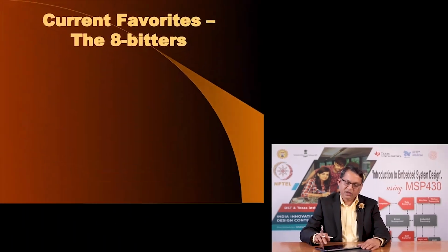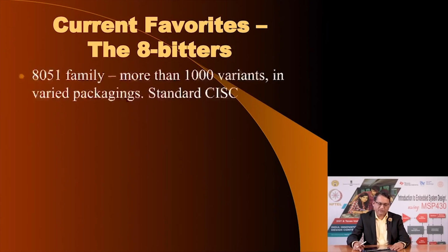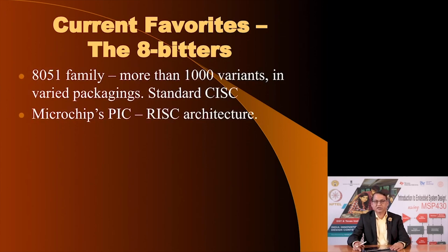So, this is a list of some popular 8-bit microcontrollers. One of the most popular and one of the oldest microcontroller families is the 8051 from Intel, although currently Intel does not manufacture any microcontrollers in this family. It has licensed the technology to other manufacturers, and more than 100 manufacturers worldwide manufacture microcontrollers based on this architecture, and there are more than 1000 types of microcontrollers in this family. It is of CISC nature.